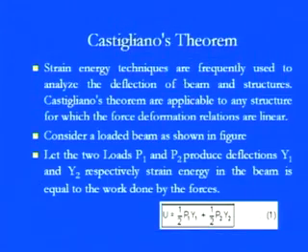Now we are going to discuss Castigliano's theorem, which is basically focused on the complementary strain energy and the elastic strain energy, in which, if any slight change is there within the elastic region, then which energy is dominating. Strain energy techniques are frequently used in analyzing the deflection of beams and structures, as we discussed. Castigliano's theorem is applicable to any structure for which the force-deformation relations are linear. So if within the elastic region any slight change is there, we can simply go with this particular theorem.